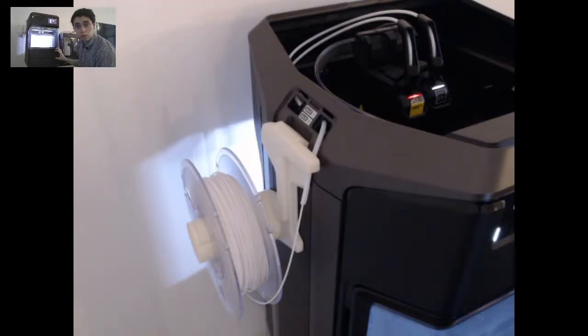Regularly, when using your material base, the filament is automatically routed into your extruder. In this case, since you're side loading it, you're bypassing a few of the sensors that the printer has. So that's why I think it's really important to manually push the material instead of waiting for the printer to automatically detect it. Once you start playing with it, I'm sure you'll see the benefit behind it.